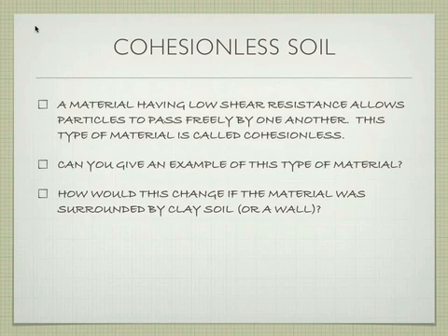What if you put this material inside of a concrete box, or for that matter, put it inside of something that was clay soil around it? Does this property change? What do you think? I'd say yes. So let's say you fill a concrete block or a bucket. Let's take a 5-gallon bucket, you fill it with sand. If you stand on it, will it support you? Yeah. So if this type of soil is surrounded by another type of soil or rock that is cohesive soil, something that sticks together, this soil can support quite a bit of weight.